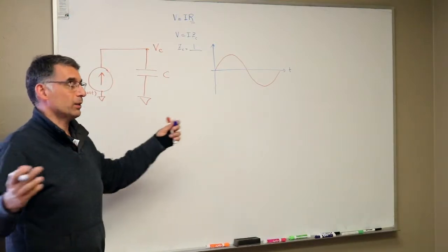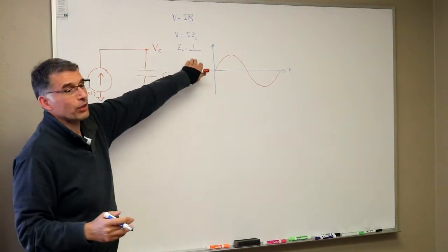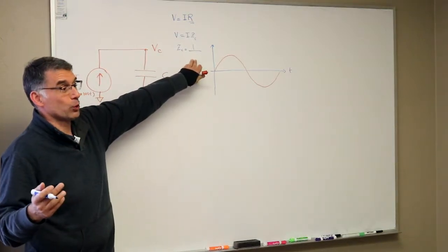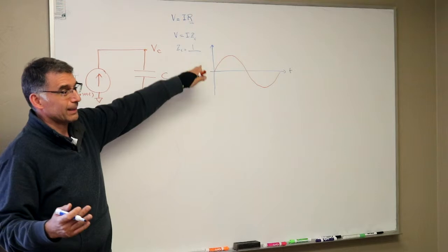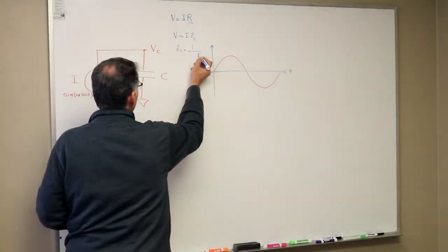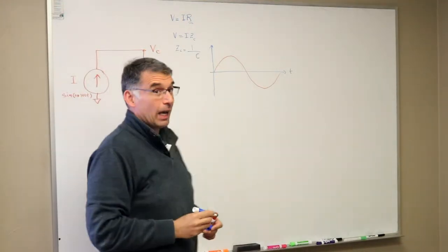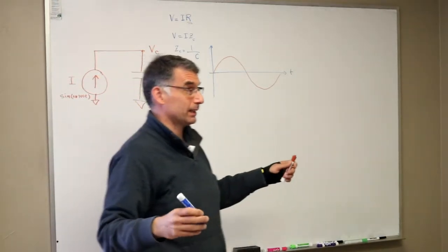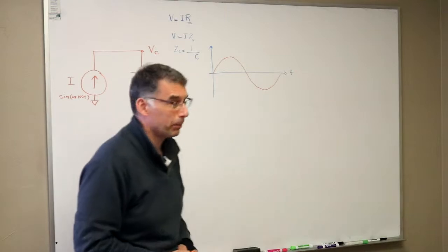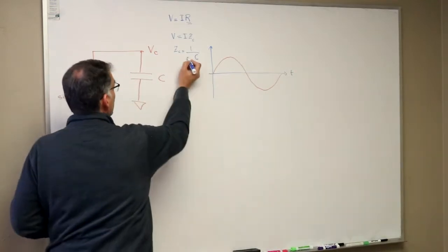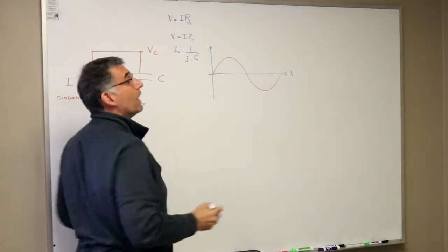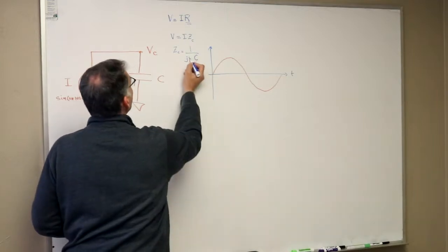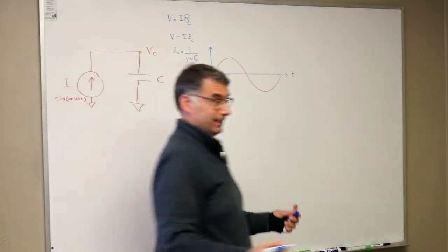Well, there are 3 terms here. Which one of them are you sure about? This is C. Okay, so we definitely have a C in there. We also know that the impedance of a capacitor is what kind? Complex. It's j, so you have a j omega, because it's frequency dependent.